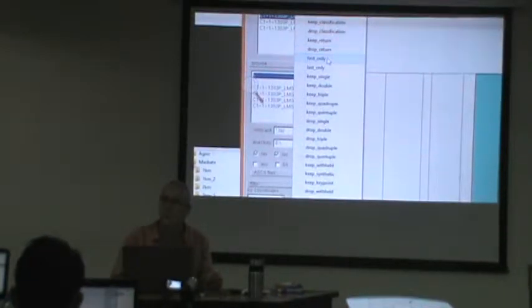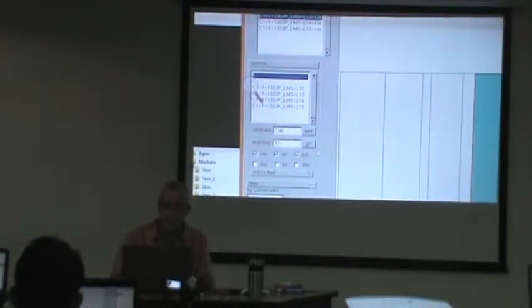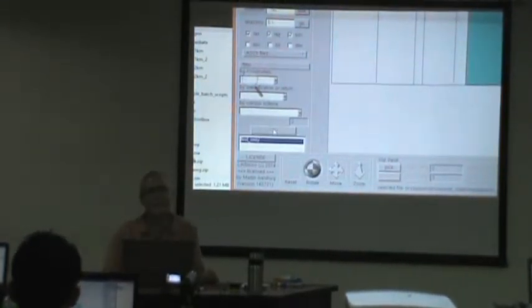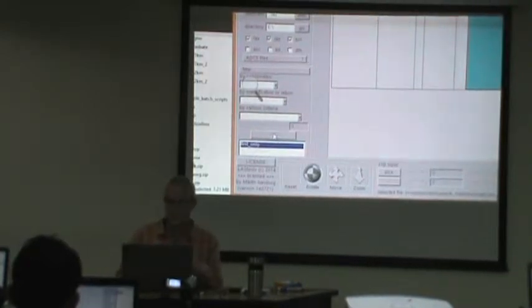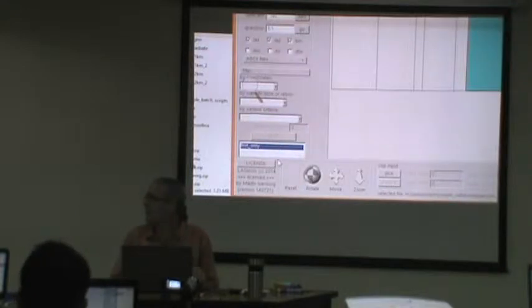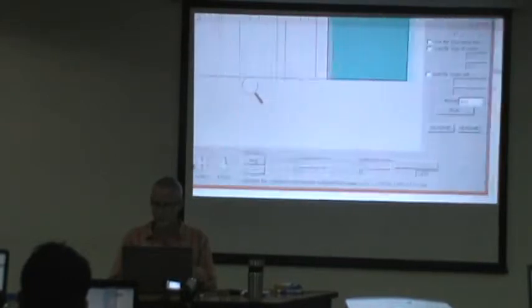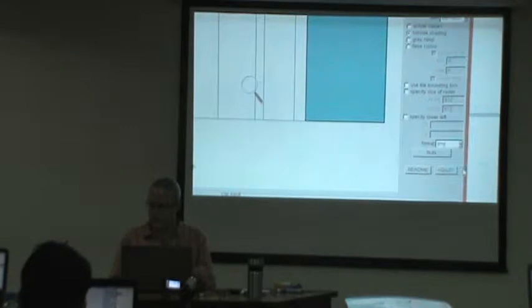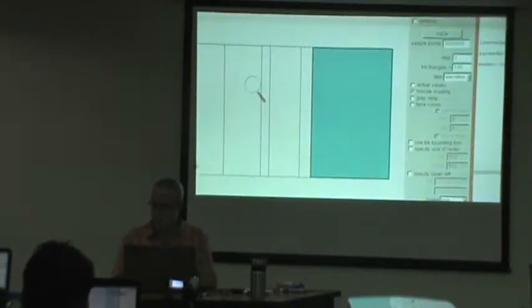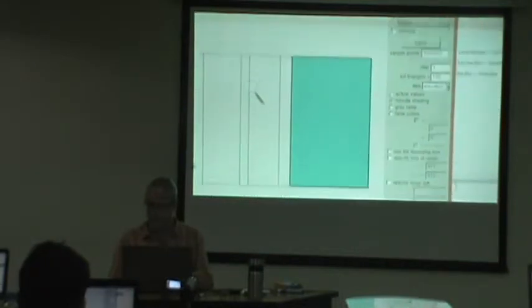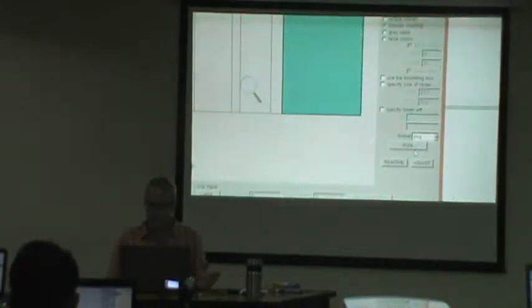What the scanner reports: the scanner records first and last returns. So I can always create a DSM before ground classification. It may have errors because we didn't remove the noise, but in the DSM we can also look at the noise. First only, I'm outputting a PNG. That's it, merge into one, first only, hillshading, PNG, run.